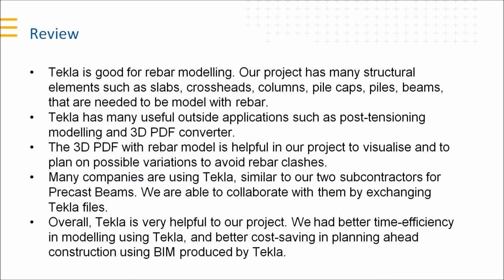3D PDF with rebar model is helpful in our project to visualize and to plan on possible variations, like to avoid rebar clashes. Especially since we are using mostly precast elements like the hammerhead I showed and all the precast beams. We can plan ahead using our BIM software to see how things are going to be built and to plan accordingly. Many companies are using Tekla. So far, we have 2 subcontractors that use Tekla Structures. We were able to collaborate with them by exchanging our Tekla files.